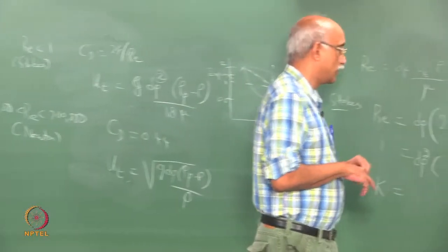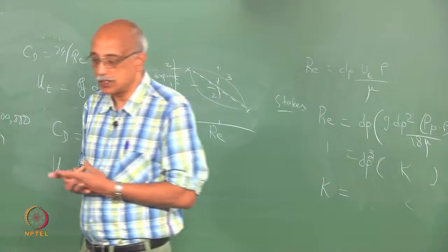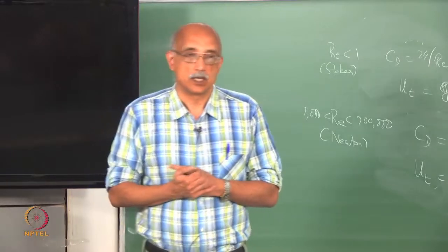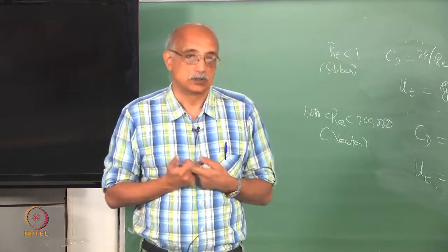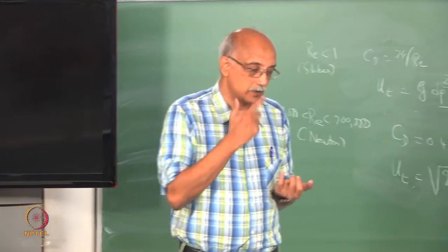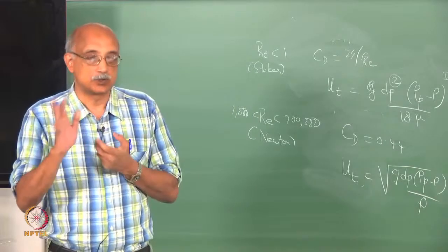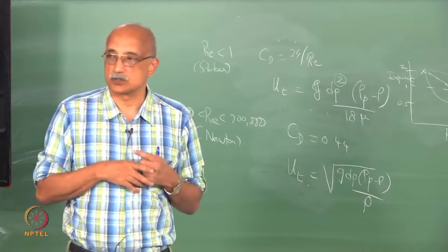Now, what are some advantages of a fluidized bed? The primary advantage is that you can go to higher flow velocities without paying a penalty in pressure drop. And where does a higher velocity help you? In one case, it improves the throughput. The more material you can pump through for a given time, the greater is your production capacity, so to speak.